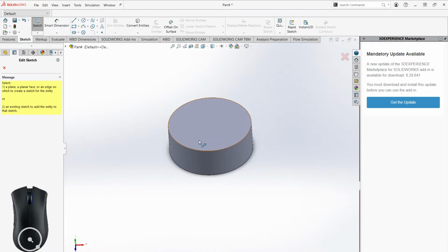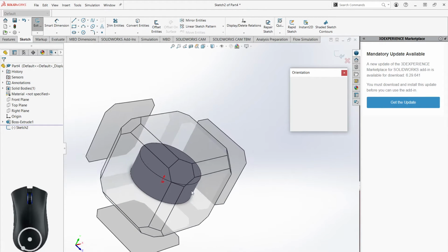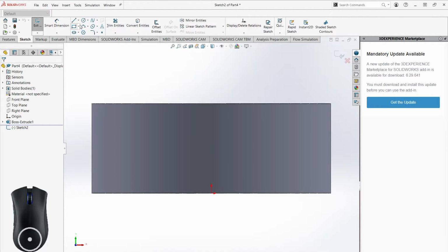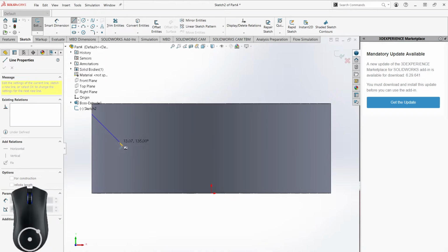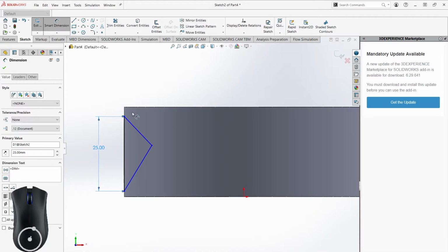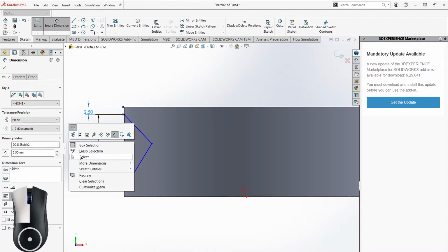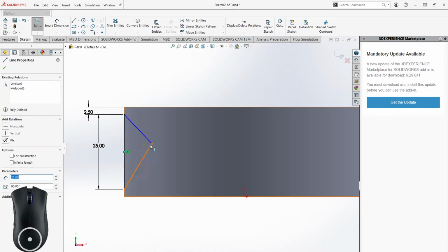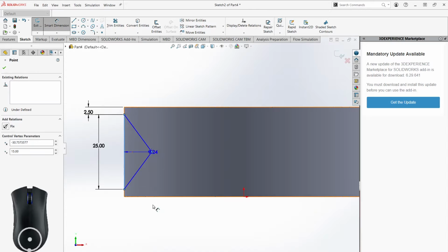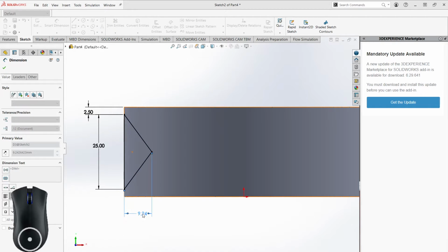And now let's create a new sketch. We're going to choose one of our initial planes here. Let's choose the front plane. Right, that should take us in the middle of this thing. What we're going to do is we're going to do maybe just a little triangle shape, right? We can keep it simple. We can dimension this, say it's like 0.5. To make this 2.5 away. You can say that the middle of this is horizontal to this, and we'll say it's 10 away.